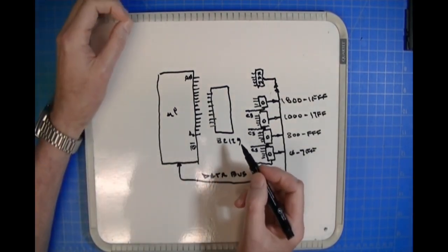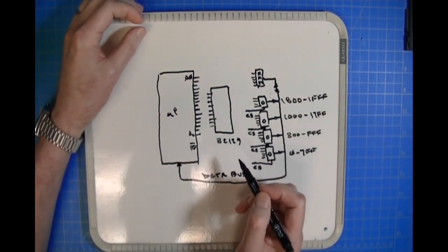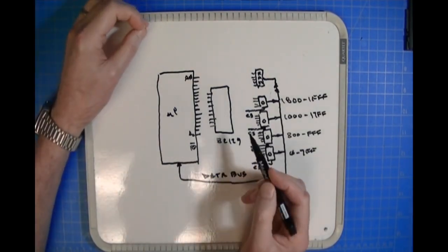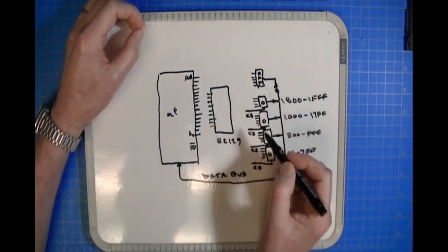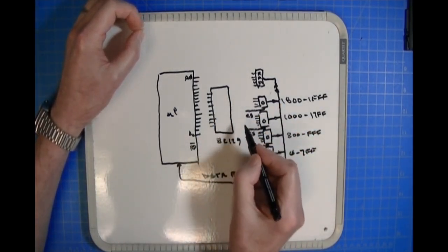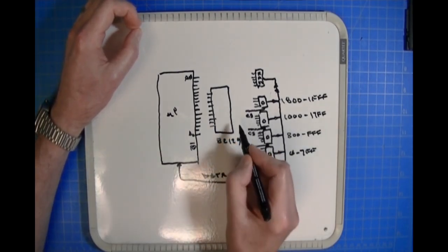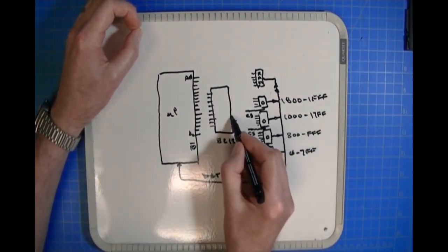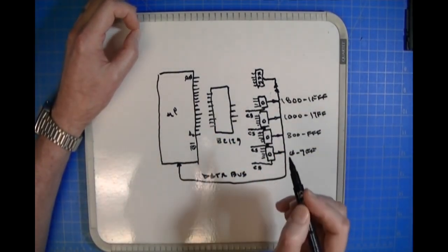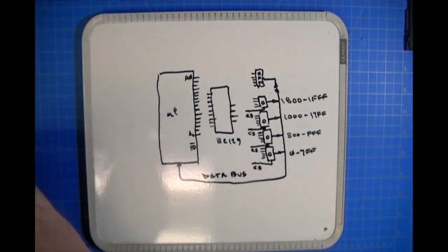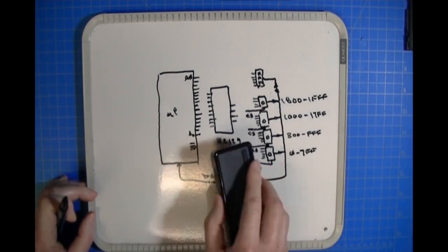This is a 256 by 4, okay, 4 bits. So maybe I picked the wrong one because I don't have another bit to address my RAM chip. But anyway, on the output of the bipolar PROM, you've got 1, 2, 3, 4 outputs. Okay, and you have, I'm going to erase this here, 82S129.